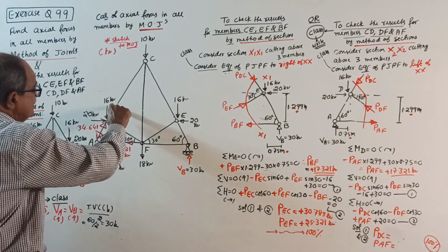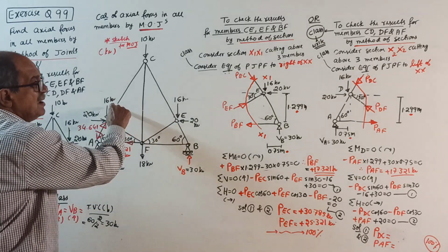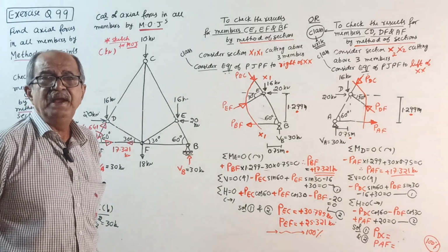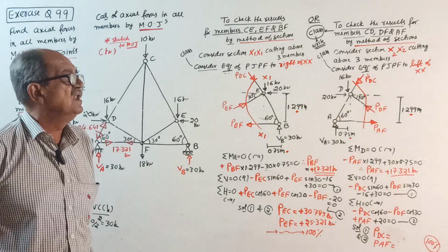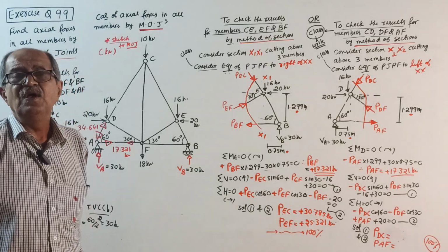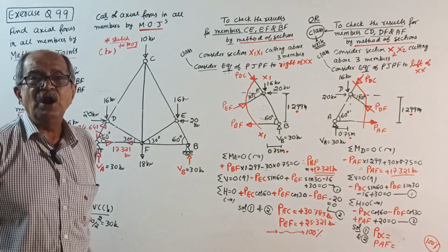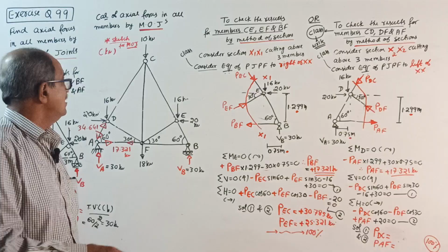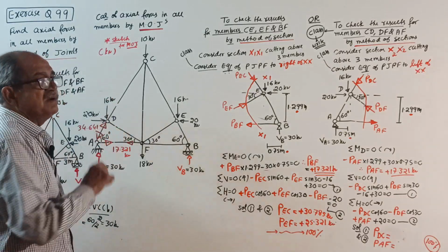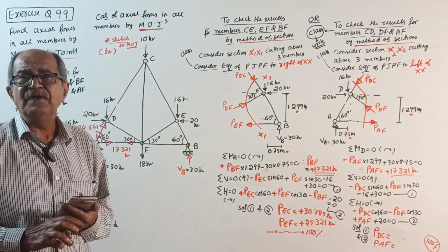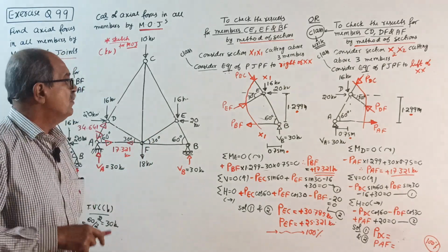Joint D has got what? Two inclined members. So the usual trick applied for one unknown horizontal, one unknown inclined, or one unknown vertical, other unknown inclined, the shortcut is there. That will not work out. A simultaneous equation will come. That is what is better you do. Every class I am telling, for me no problem.